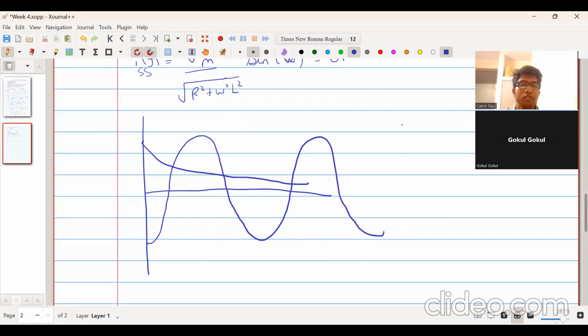So that is the other component of the current. I of t, and this is time t. So at time t equal to 0, suppose this is plus 5, this will be equal to minus 5. That's why the actual current at time t equal to 0 will be 0. It will be here somewhere. And then the current will have a curve like this, will go a bit up and come down.